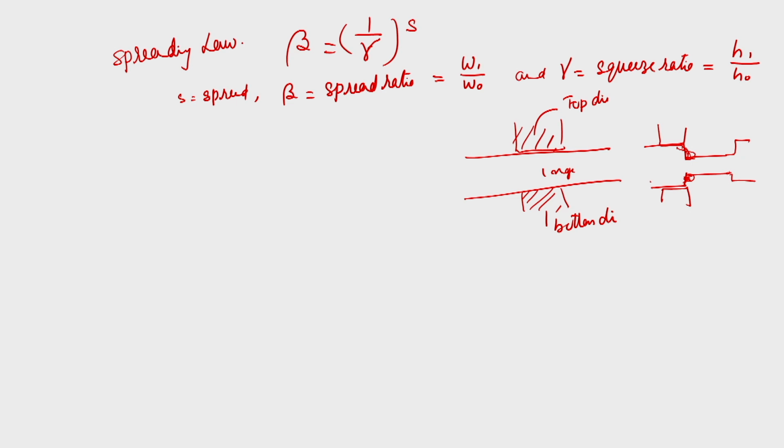These laps will form if the deformation is above a certain critical deformation, a critical strain. Below that it may not happen, but above that it will, because sideways barreling also takes place and that always causes this. So if your strain is very large, there is a chance of lap formation.